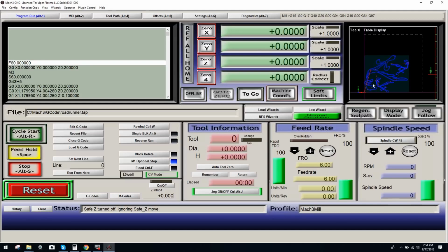Mach remembered exactly where it was, and now what you're going to do is hit your machine coordinates again. It's a good practice to get into, even though you already know you didn't reference anything. It just gets your mind in that muscle motion, so to speak, as far as that mind-muscle connection. And once you're back there, you can click it again, cycle back, go back into G54 where the button is not illuminated, validate it, and now hit ref all. Once you do that, you are back in the same position, and Mach is ready to go.